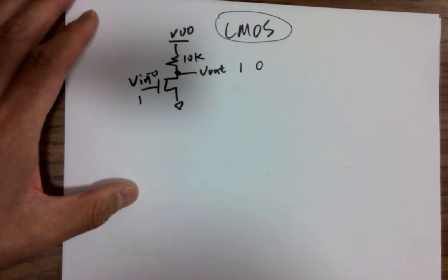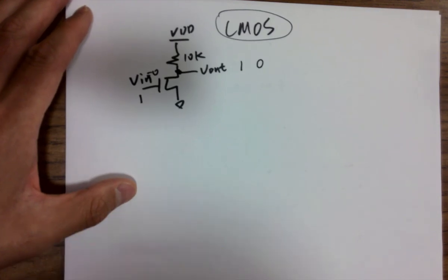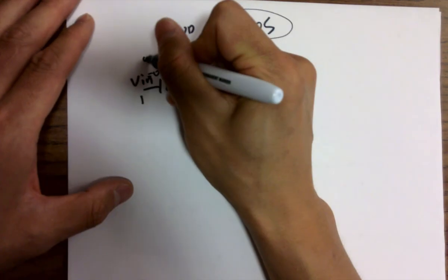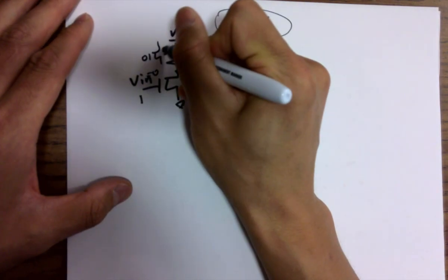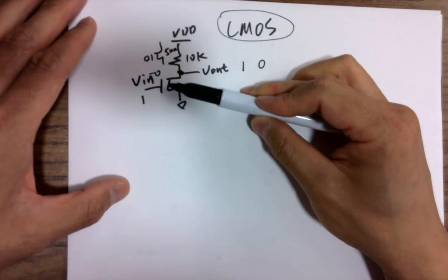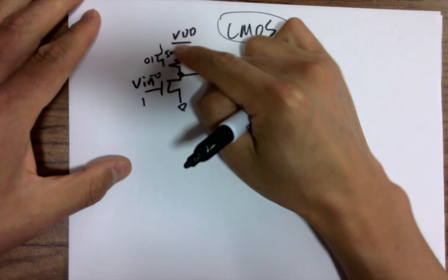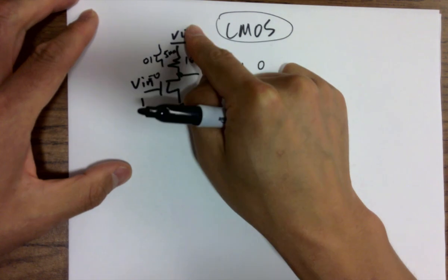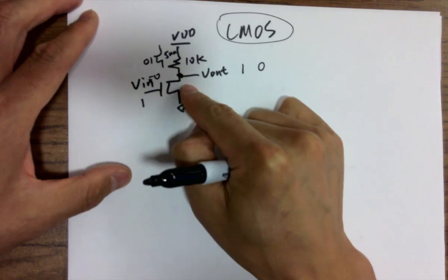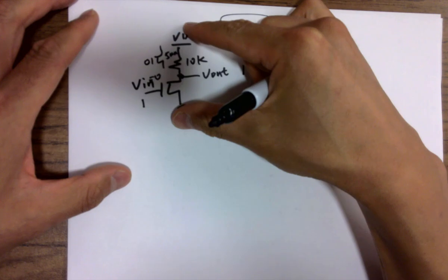And another one is resistors take a lot of space. If you're thinking about using N-well resistors, they are maybe 100 microns in length. But nowadays, a little PMOS on the top is probably only 5 nanometers as the smallest one. So you just use a PMOS and NMOS as two complementary devices, one on the top to pull up the pin to VDD, another one, NMOS, at the bottom to pull it down to ground, to form a very basic logic gate.